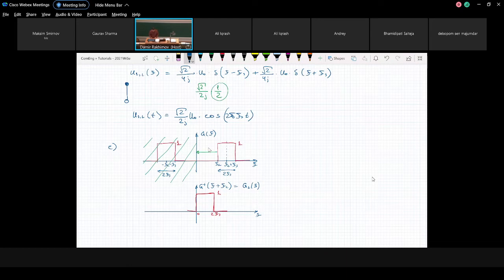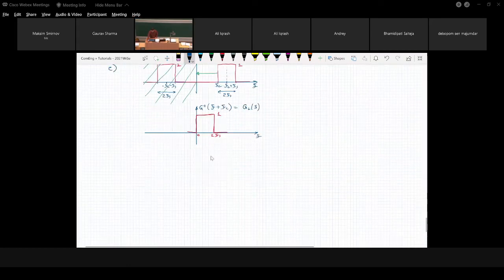That's all. So this is our corresponding transfer function. But it's not conceptual, because depending on the numbers you will have different results. If you performed the transformation with respect to frequency FC plus Fs, then you would get a triangular pulse centered at the origin. But here we have a pulse centered at FC plus Fs, and we perform the transformation with respect to frequency Fc, our transfer function.